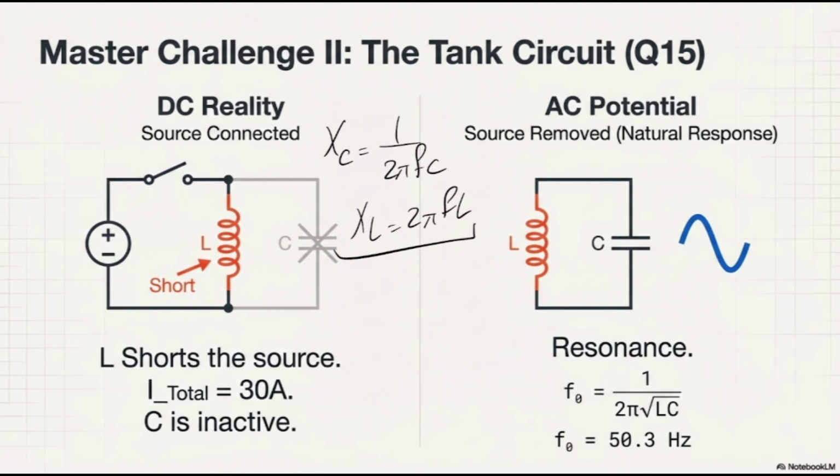It means that at what frequency I can say that inductor and capacitor can cancel out each other, because X of C and X of L have the same magnitude, while X of C, the reactance of the capacitor, is negative, while the X of L, the reactance of your inductor, is positive. At one point, these two can be equal.